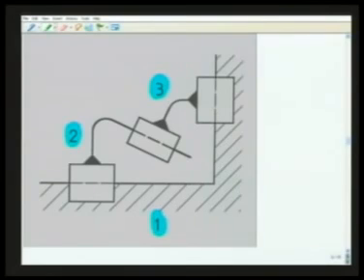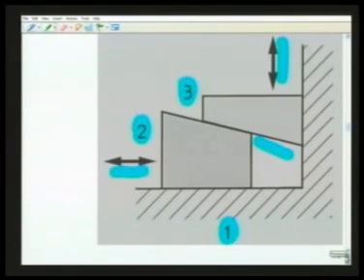It is obvious that here relative motion between various links is possible. It is not a structure. The degree of freedom of this loop is not 0. As we can see, link 2 can be moved in the horizontal direction to produce a unique vertical movement for link 3.